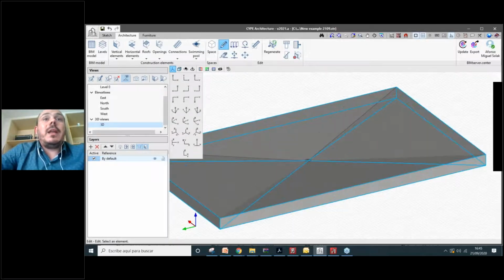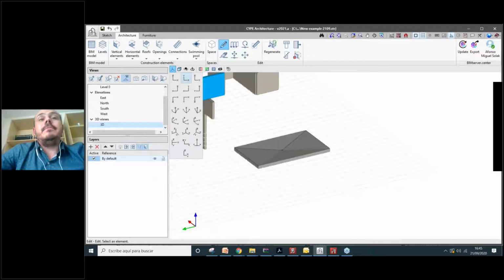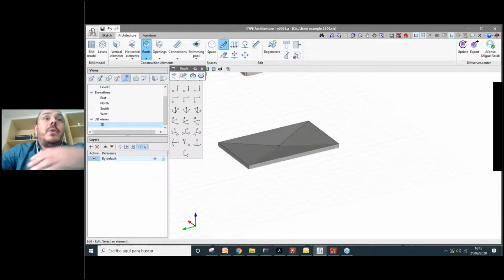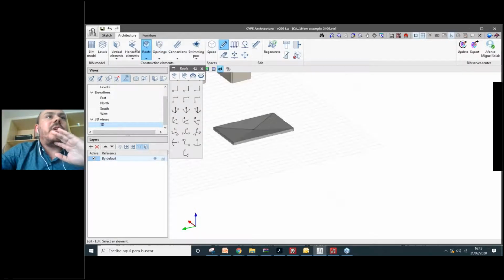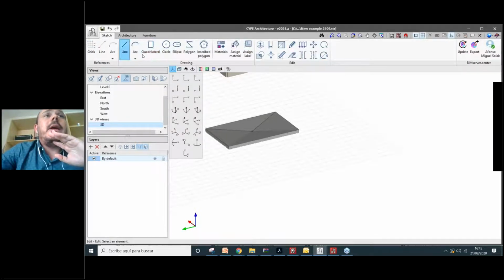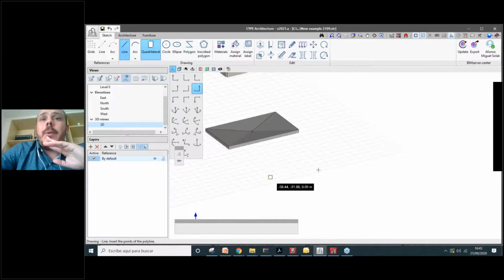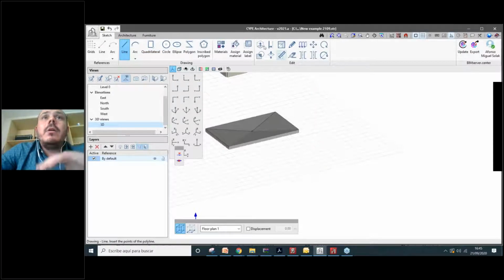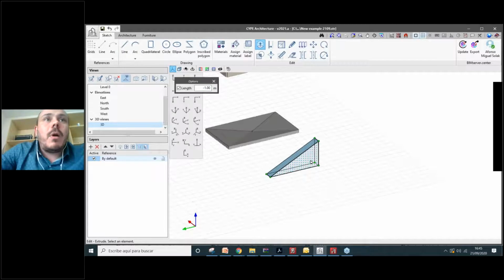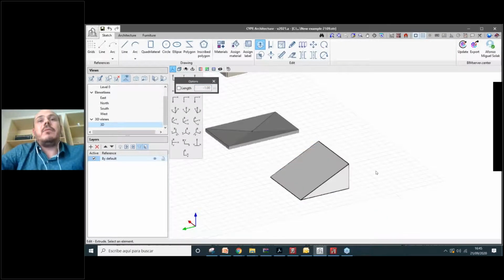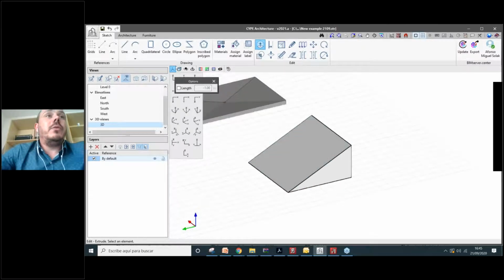So it's very good for flat roofs to generate this kind of drains. Okay, but we can also have roofs with tiles. So to create a roof with tiles, I'll create first, for example, a generic plane that is going to be based on a triangle. So for example, here I will create this little triangle, and I will extrude this triangle. Oh, this is too small. For example, from here, I'll create this triangle here. It's going to be the reference for our roof.